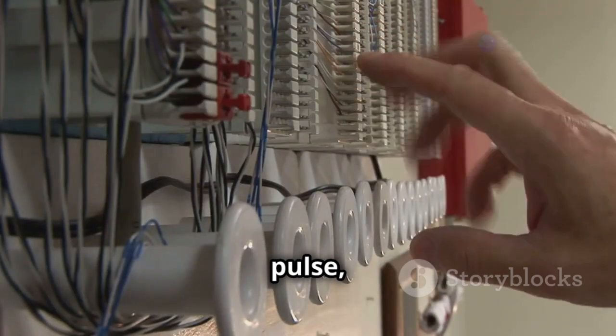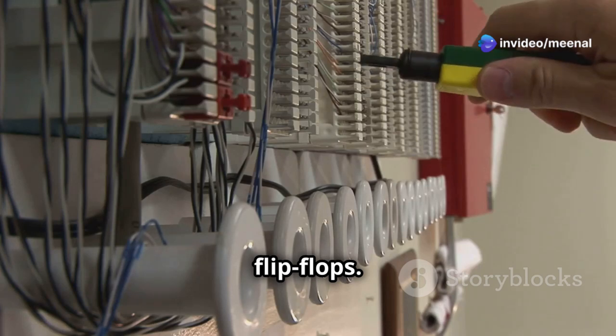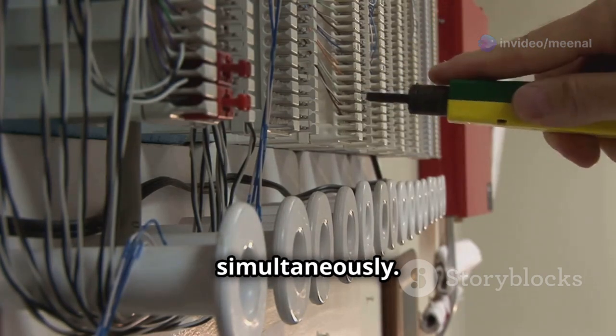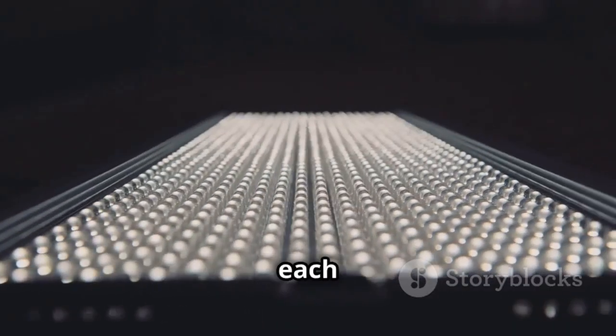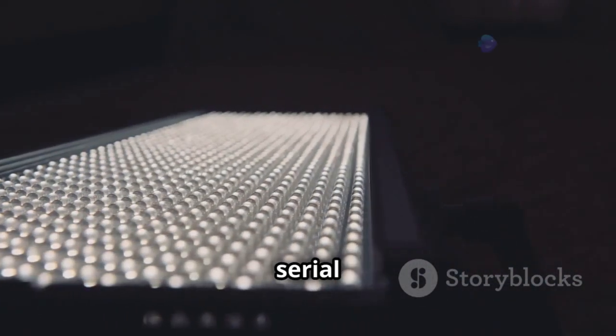On the first clock pulse, the data at the parallel inputs is transferred to their respective flip-flops. This clock pulse acts as a trigger, ensuring that all bits are loaded simultaneously. Subsequently, with each clock pulse, the data is shifted towards the output, resulting in a serial output of 1010. This shifting process continues until all bits have been transmitted.